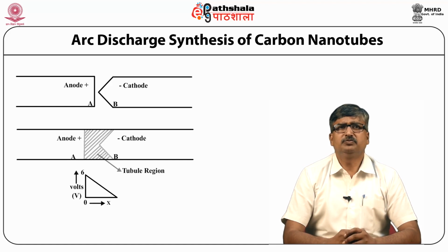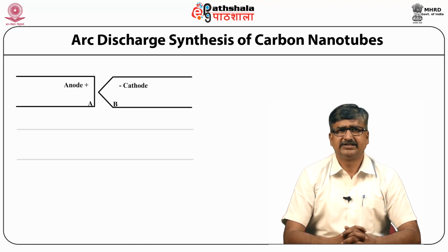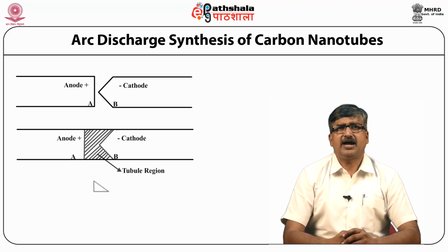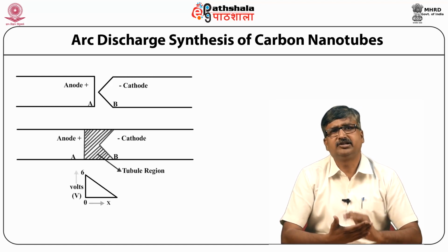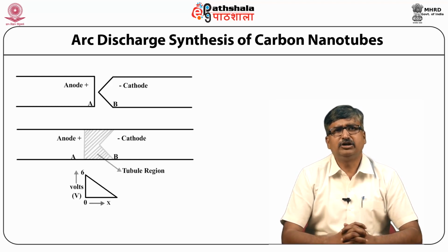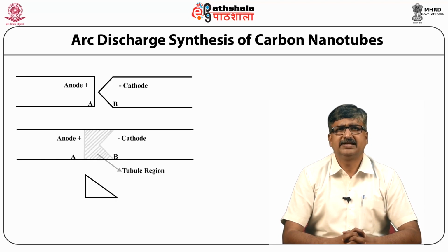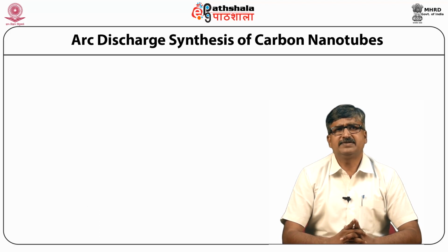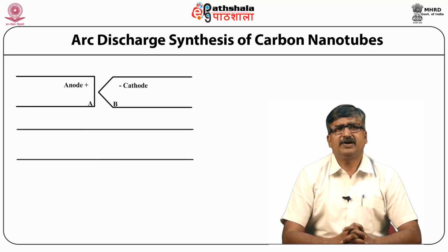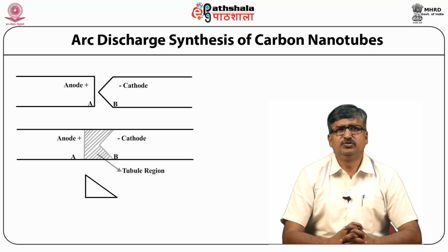The carbon nanotubes were produced by direct current (DC) arc discharge in a helium ambient at a pressure of 500 torr. Two graphite rods, which are visible in the figure, were used as electrodes for arcing. The positive electrode is of the order of 7 cm length, 0.7 cm breadth and 0.7 cm height, and the negative electrode is 5 cm length and 0.54 cm diameter.